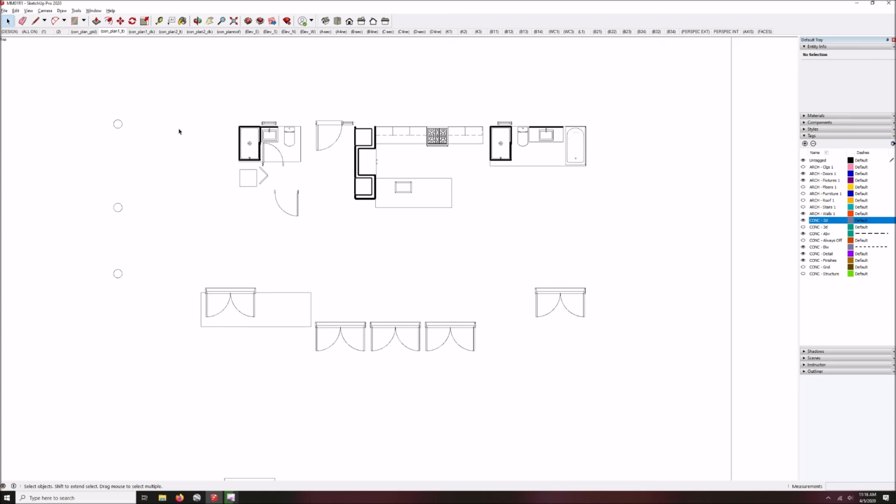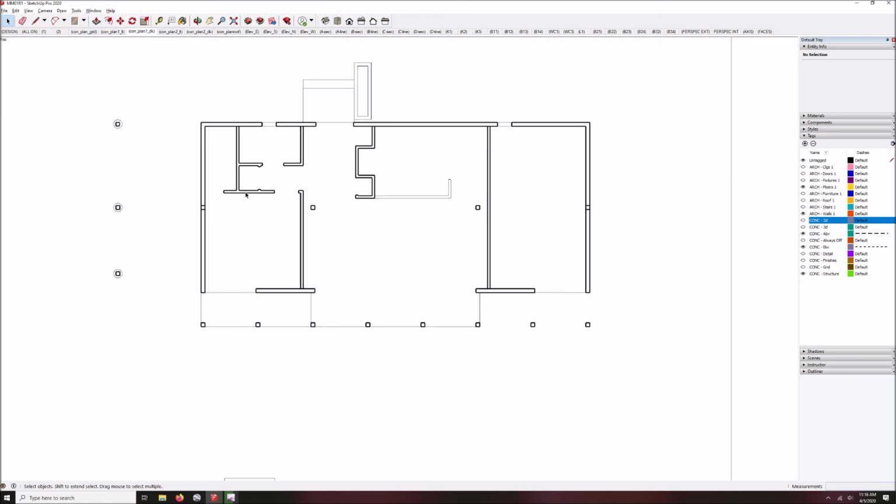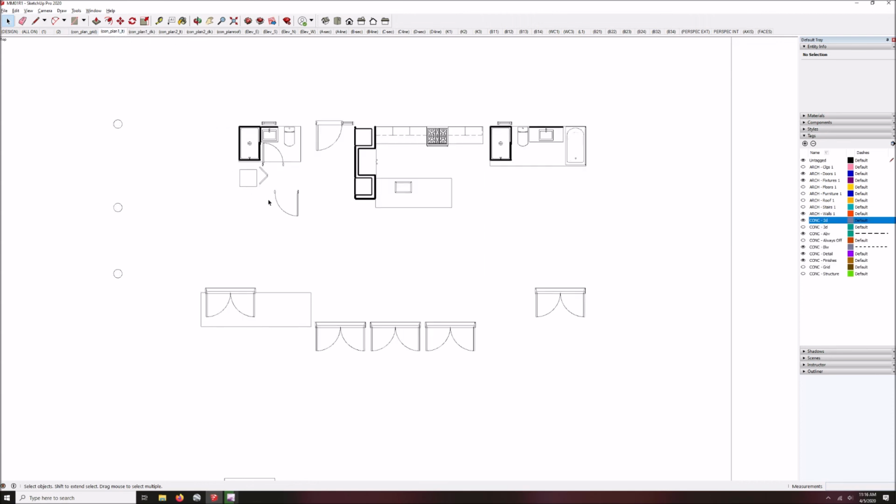And that will be overlaid with another view of the same, taken at exactly the same spot where I have the walls, and the walls will show up as a thicker line. And when I put those two views together, those two scenes that we see up at the top together in one construction drawing, we'll end up with a nice, clear, thick, solid line indicating the walls, and thinner lines to differentiate the plumbing and the kitchen cabinets and the doors and windows.